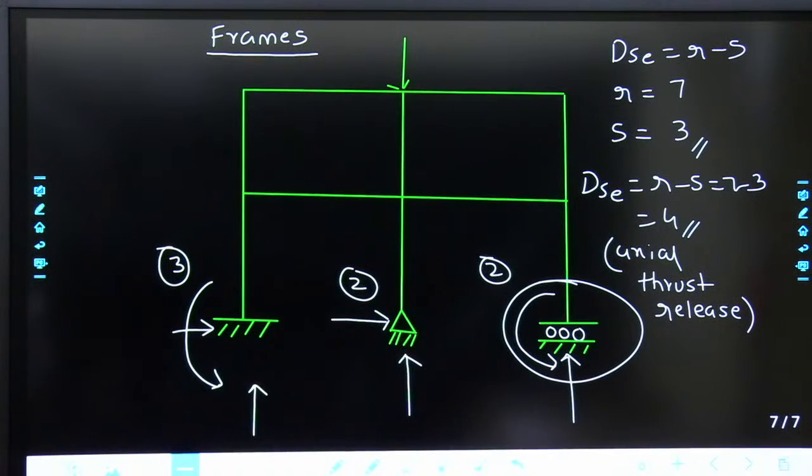Generally, that happens in beams. We will not be worried about it in trusses actually. In trusses, for purely vertical loading or anything like that, we will take 3 only. In beams, if it is purely vertical loading, we will be taking 2. Once again I am repeating, for beams if it is purely vertical loading, then you will take S as 2. I have not gone up to that case, I will be very clear at that time.